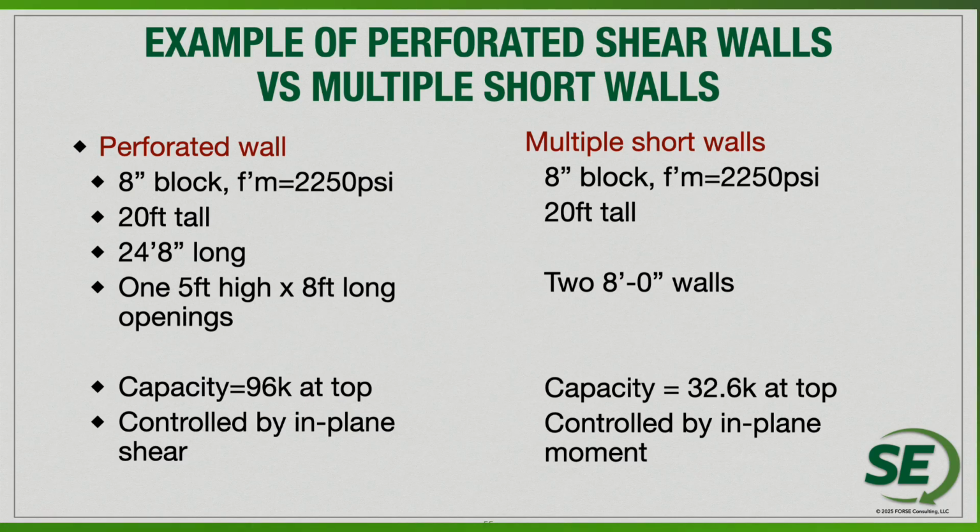Now again, back to an example of maybe a big box retail store, maybe that's not that important. Maybe we can just use individual wall panels and just not necessarily consider perforated shear walls. But there's going to be plenty of projects where we work where maybe the only masonry is a stair and elevator shaft with several openings. Making sure that we keep a perforated shear wall in those shaft walls is going to be adding a lot more capacity and stiffness than having multiple short walls in an elevation.